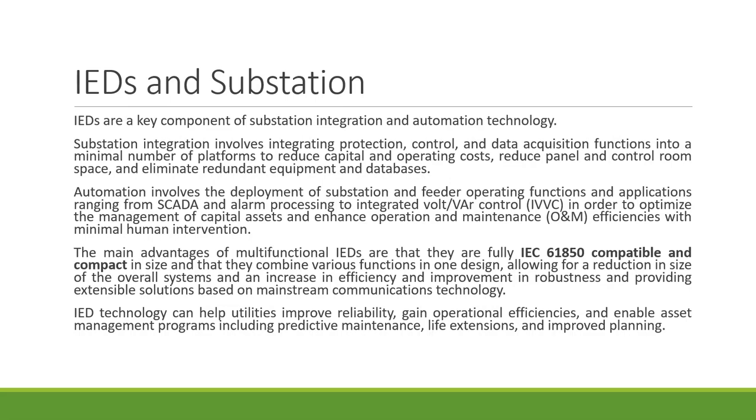Whatever is not needed exactly, you do not need certain databases, the data which you are collecting but is not required, so no need to collect that. That can be avoided when you go with substation integration and automation with IEDs.